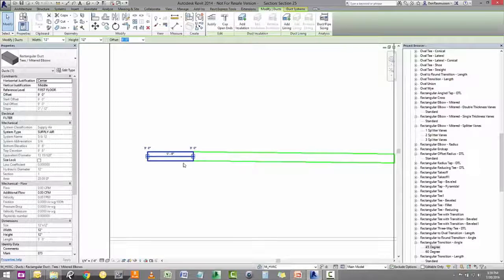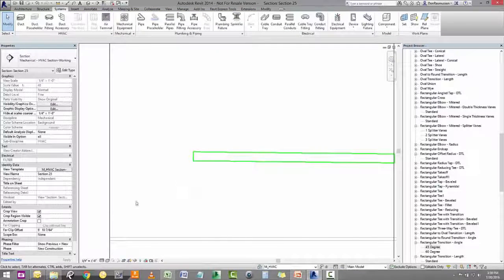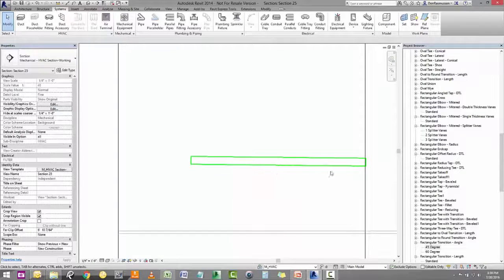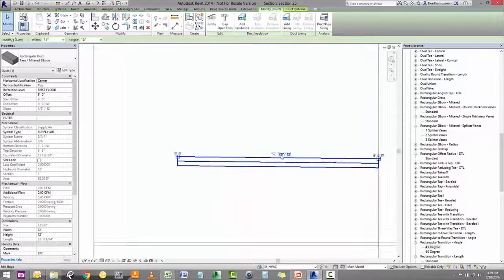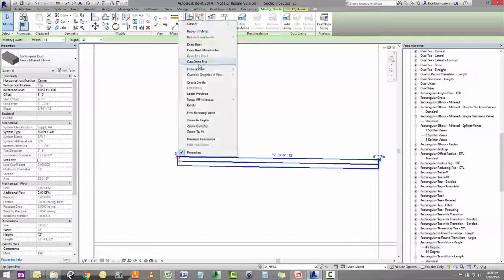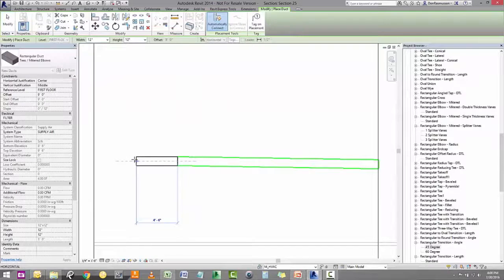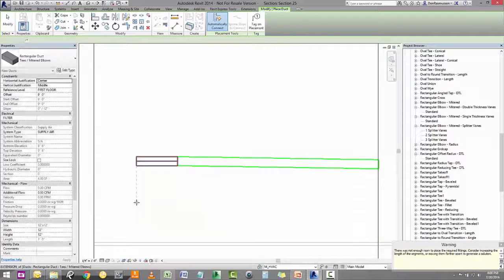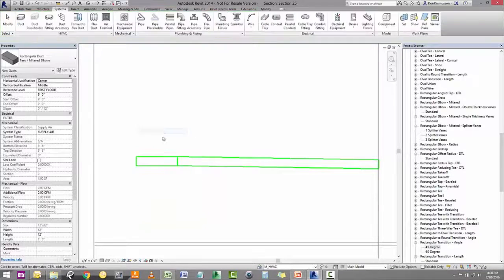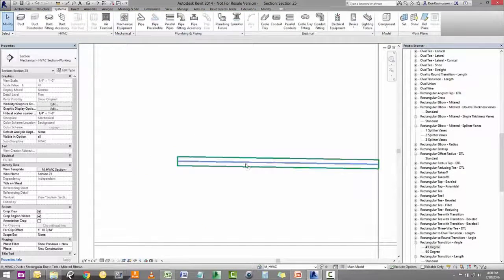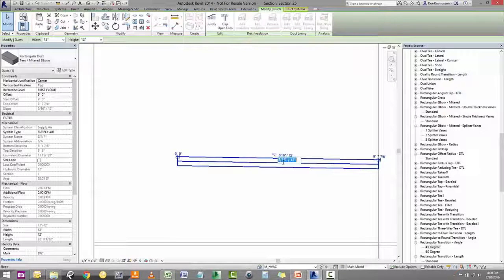And this is really kind of a restriction as far as drawing slope ductwork inside of Revit. If you want everything to stay connected, there are some limitations to what you do. So if it's at an 1/8 inch here, and let's increase it to 3/16 here and see if it works. I don't think it will. I right click here, draw duct, and it probably still won't want to make that fitting. Yep. Usually 1/4 inch is the minimum of which you can slope duct inside of Revit, and then it starts to understand, or at least have enough room in its mind to go ahead and place a fitting in there for you. So I'll change this to 1/4.